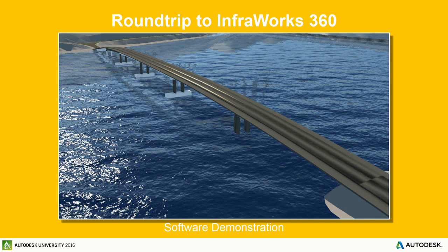If you didn't have that and you just had Revit, you would have to build the Revit bridge from the Revit perspective and not have the site conditions, which means you have to bring in the site conditions, build the bridge, and then take a look at it from that context. Why not use the powers of InfraWorks to very quickly build the bridge design and let it give you the base modeling information if you need to bring it straight into Revit? That's a lot faster than trying to build it from scratch in Revit.